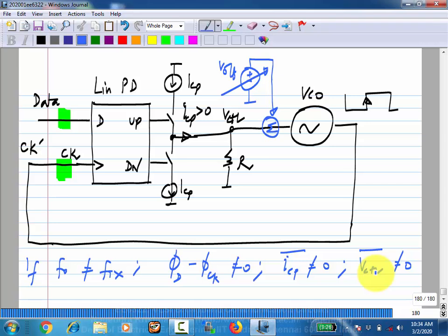So if I need this kind of control, I have to observe some quantity, some measure of error, and based on that I have to control something. That is, I have to continuously adjust this quantity until this error becomes 0. So the block that will help us do that is an integrator, right? The integrator has to be driven by this error. Any of them is fine. They are all just proportionally related to each other. So I can take any of these things, integrate that, and add this offset. Okay?